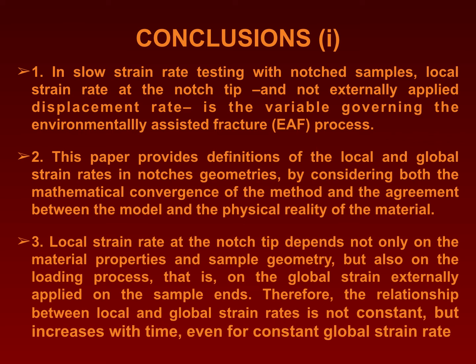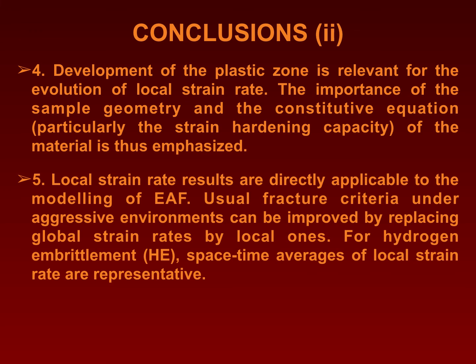3. Local strain rate at the notch tip depends not only on the material properties and sample geometry, but also on the loading process, that is, on the global strain externally applied on the sample ends. Therefore, the relationship between local and global strain rates is not constant, but increases with time, even for constant global strain rate. 4.